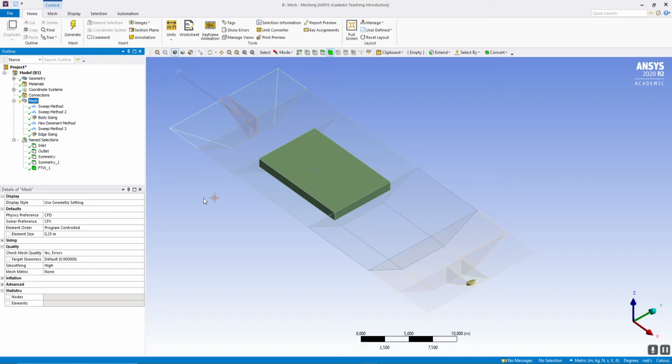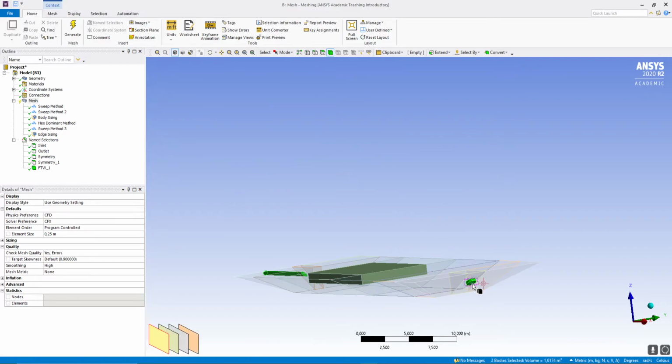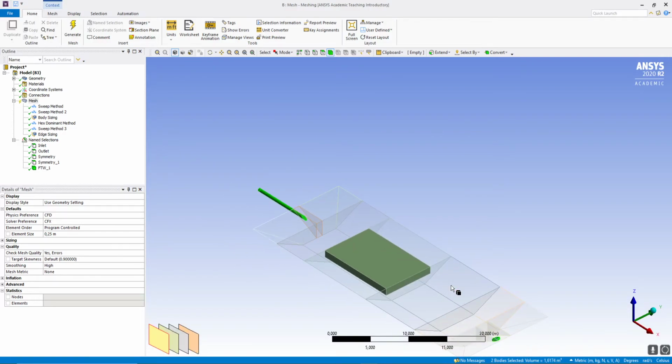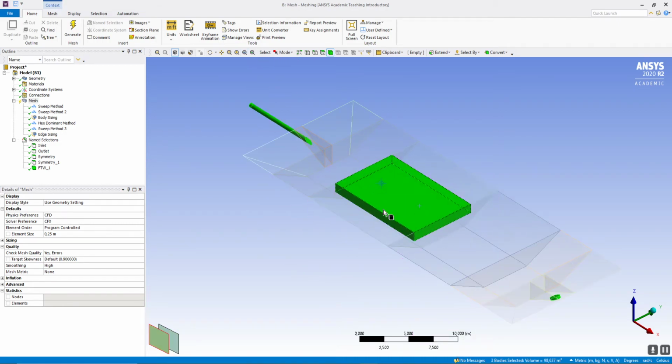Now we're going to generate the mesh, but like I said before, we need to generate this mesh in the proper order. And what is the order? The order goes from the regions of interest and the critical regions to the lesser ones. All right, so in our geometry here, the critical regions are the inlet and outlet pipes, and the region of interest is the vegetation. Okay, so these are the regions that will need to come first and will dictate the order of our mesh generation, right?